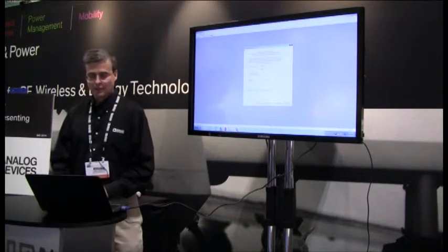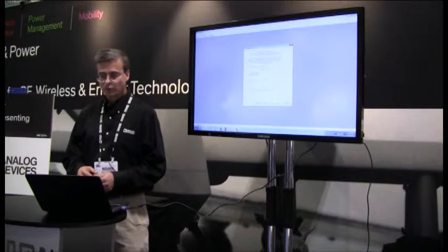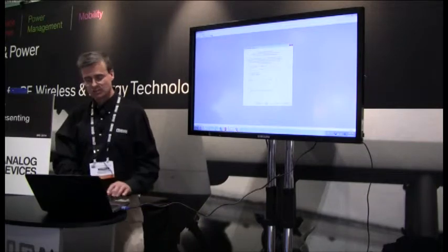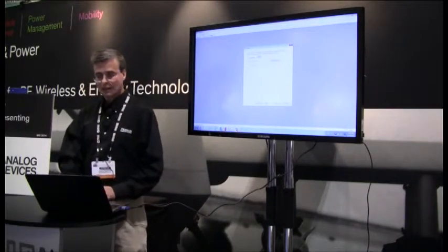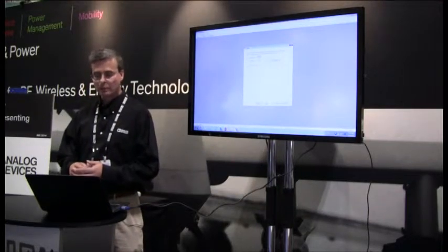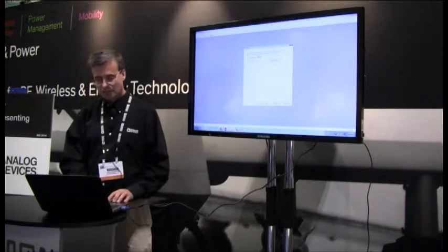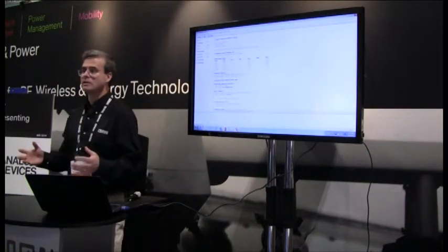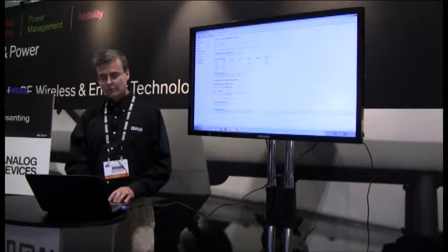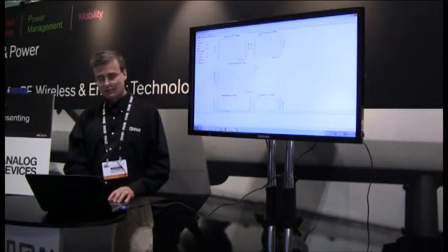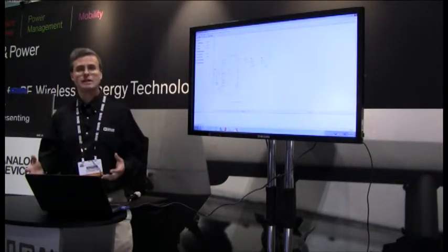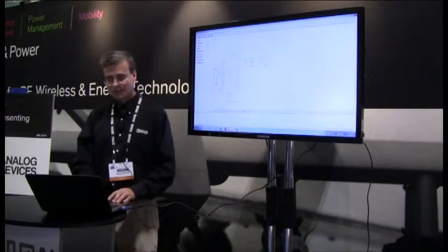Next, you're able to choose the frequency of your reference, and you have options to either pull one out from a library or do a custom one as well, and I'm going to do a custom one. You're also able to choose the loop filter bandwidth and the phase margin. So basically you're able to choose any of the parameters that are going to affect your PLL, and once you have done that, you're able to get the frequency domain and time domain response, you're able to get a schematic, you're able to get all the key factors that you need when you're designing a PLL type circuit.